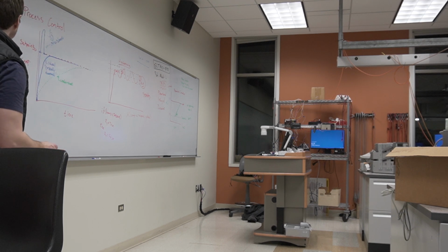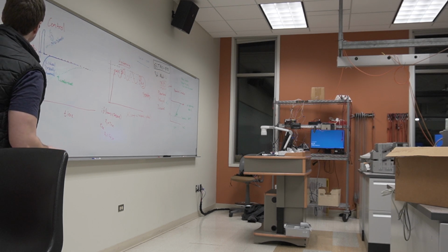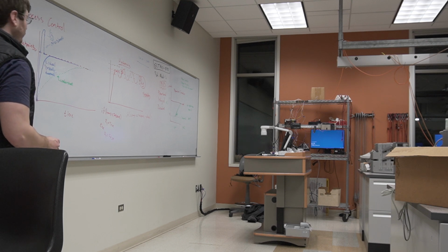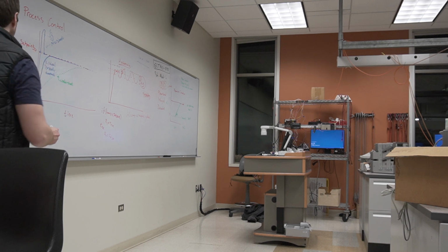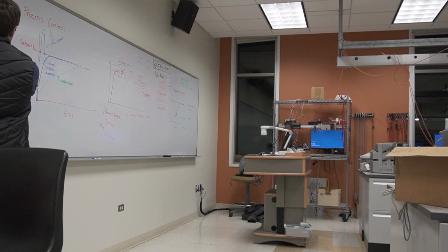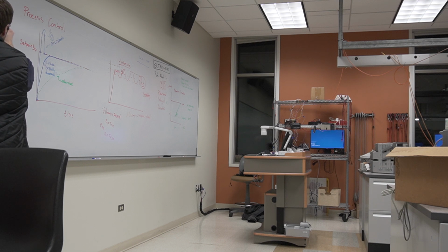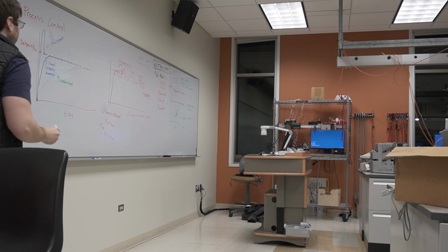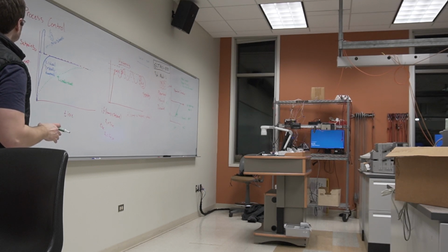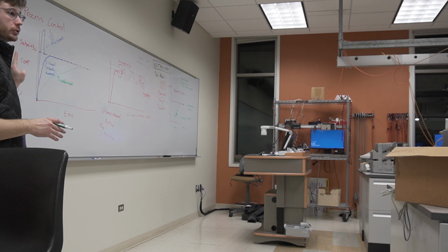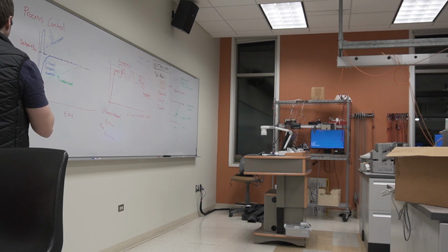And we try to say if we nudge this, if we put a force on this, that the motor will try to correct that force back such that it's upright, right? That's our system. A proportional controller, theoretically, if I push this way with this much force, would return this way with approximately the same amount of force, okay? Or again, if I push it this way an inch, ideally it would try to correct this way by an inch, okay? However,